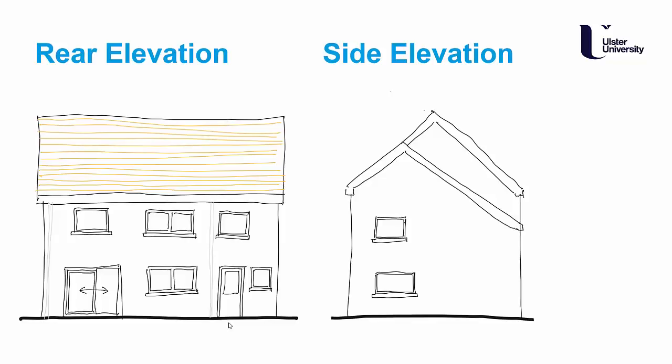In Northern Ireland and the UK and in many other countries, you do have the requirement for level access, but there's also a requirement in the UK context anyway, that you should be thinking about the level of your damp proof course, the DPC. So you should really be showing a distance of 150 millimeters between the internal floor level and the outside ground level. I have omitted it just on these rough sketches at this stage though.